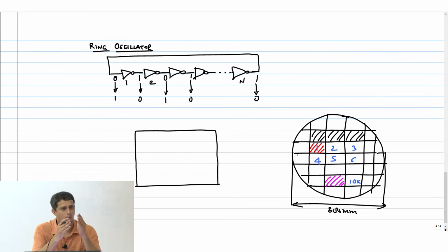So your level 1 model, like we spoke about, has a parameter VTH0, gamma, this, that. VTH0 can shift slightly, right? Instead of 300 millivolt, it can become 350 millivolt. All the transistors in that chip, by the way, that's what I mean here. Every transistor in this chip 1 can have a VTH0 of VTH plus delta. This magenta guy, every transistor in this can have a VTH of VTH minus delta, right?